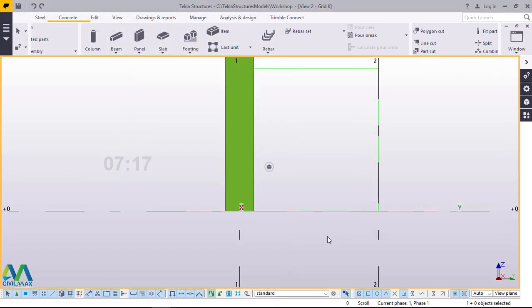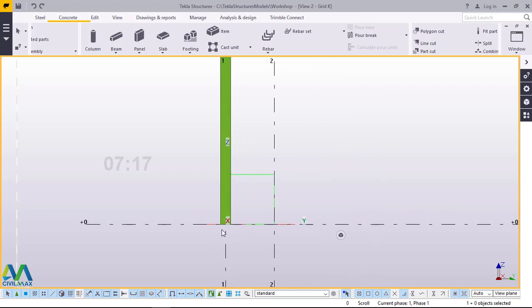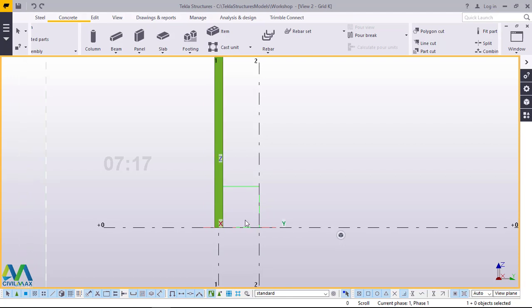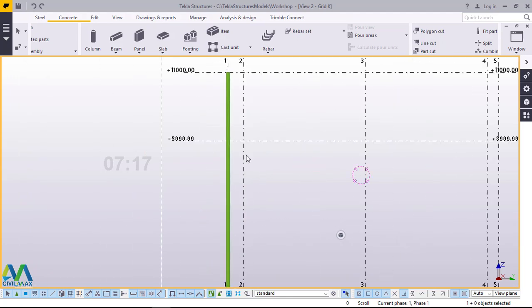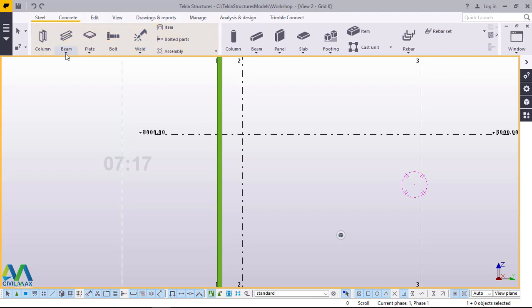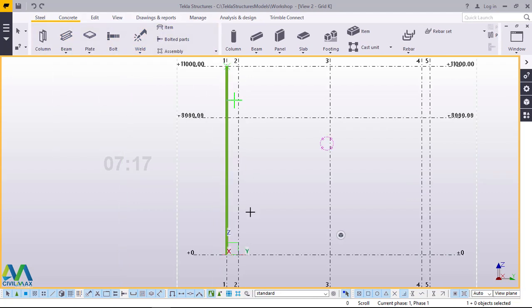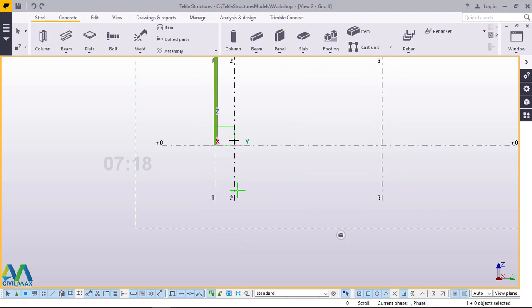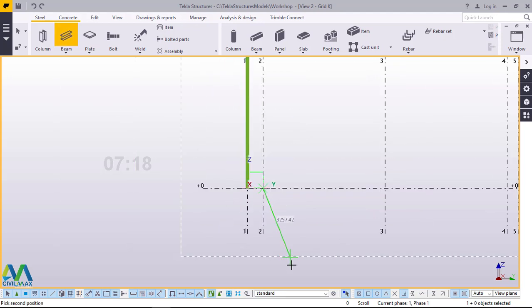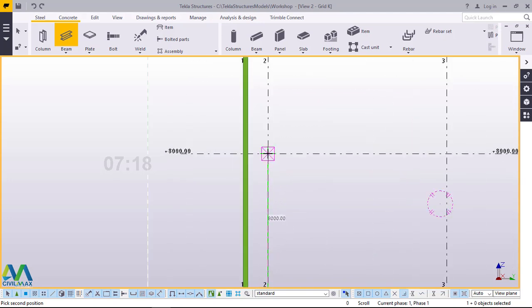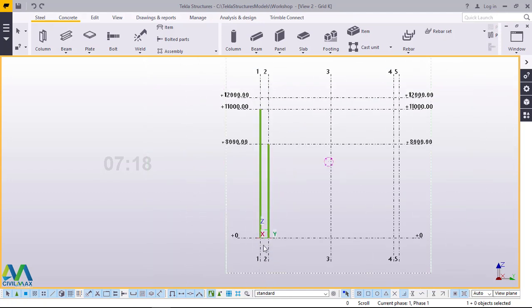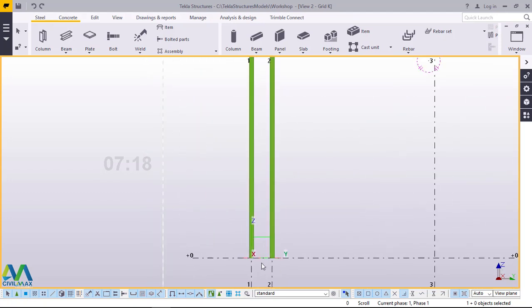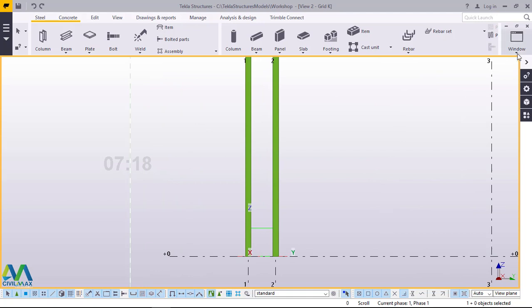and accept here. Now we'll use the same profile of the column, but to a different height. We'll take it to a height of 8 meters. We'll go back to style again and come to beam and pick beam right there, and start it from right bottom here. We'll pick it from that spot and run all the way to this end and snap right there. Right click, interrupt, just walk away from that beam command. Now we'll switch back to isometric view so that we'll be able to see how these two columns sit on the locations we've placed them.